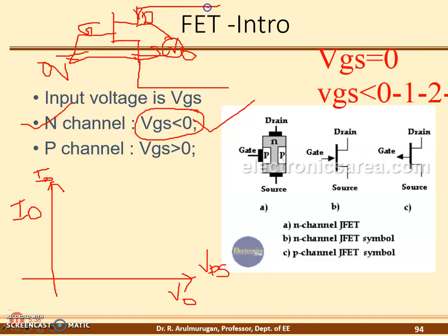So drain to the source, I am going to apply the source on the drain. Drain to source means what happens? Here the output current versus the output voltage increases linearly. It increases linearly, okay, and after that what happens? The output current is saturated.